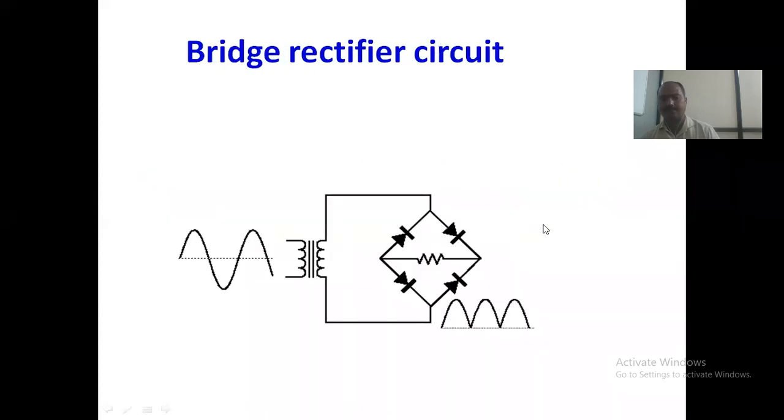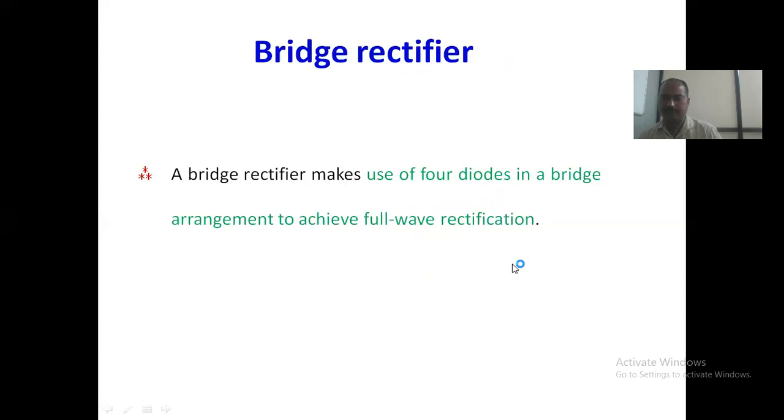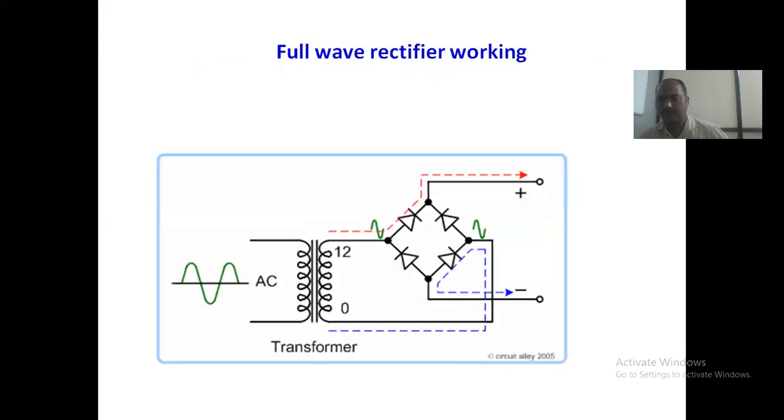We know that for diodes used in a bridge type configuration, see how it works: at a time only two diodes work, and we generate the output accordingly. That should be animated here. Depending on the positive or negative half cycle, only the upper two or the lower two diodes work. Any problem on the bridge, center tap, or rectification? No problem related to the rectifier.